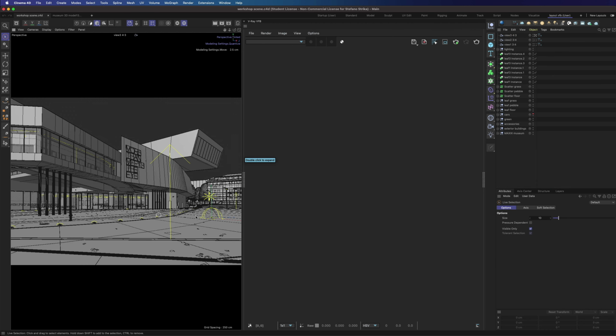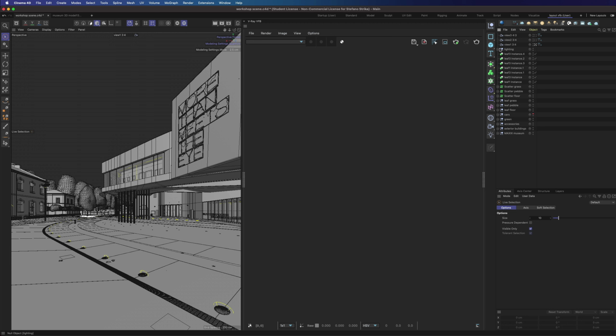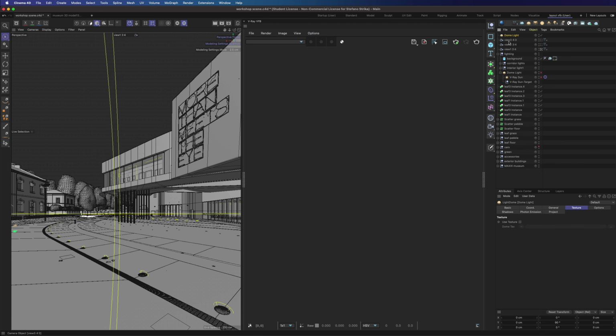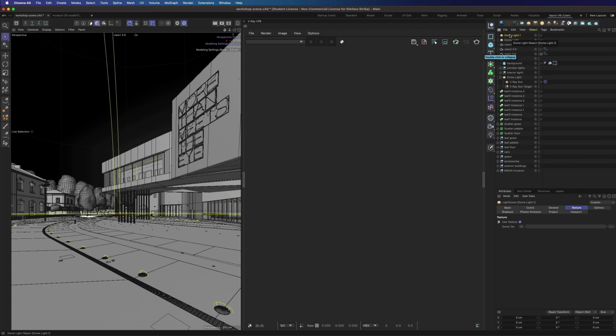Now we added our physical sun and several artificial lights. We still need to add neons and IES lights, but first of all, let's test another lighting option using an HDR sky. Let's turn off the sun sky system. We can simply add a dome light where an HDR texture can be loaded, but I prefer using a custom setup that was kindly shared by Unal that not only has all the dome light functions, but also other features that I will show you.